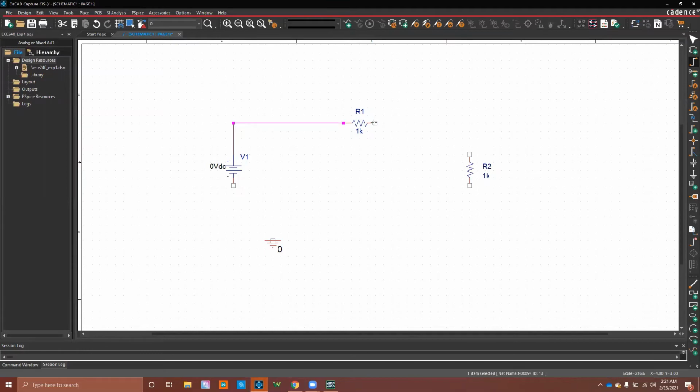So continuing on, I'm going to left click on the box, go down, connect them, go down here, and I'm not going to connect it to the ground like this. What I'm going to do is just continue on to the source. Okay, so now I have all of these connected like so. And typically with the ground, we like to get a small wire and just connect it right here. So now this whole bottom part of the circuit is connected to ground.